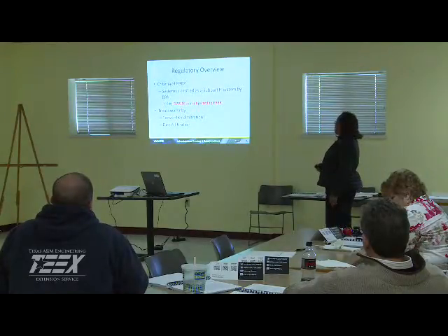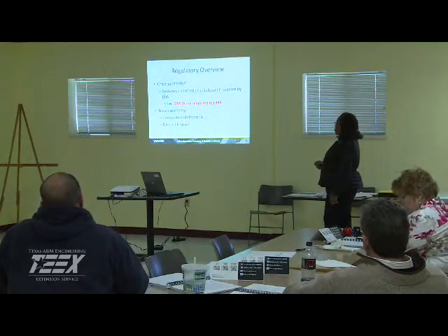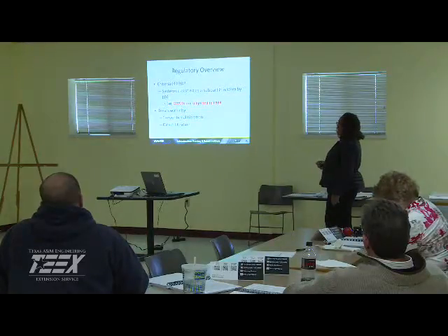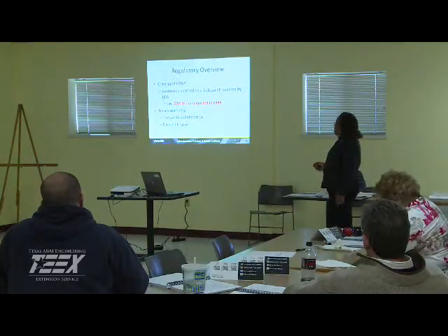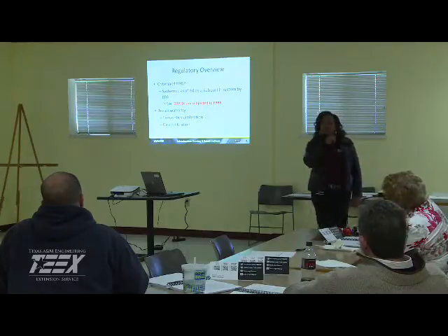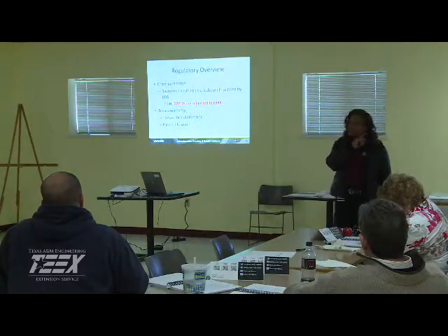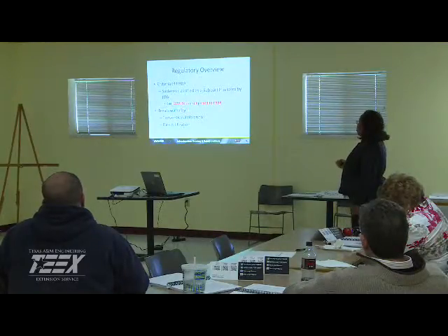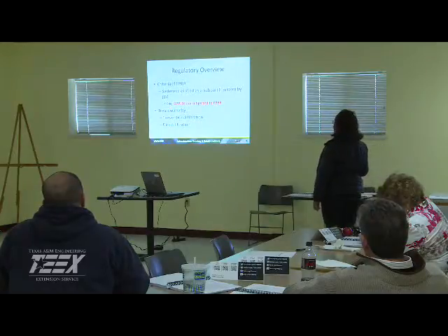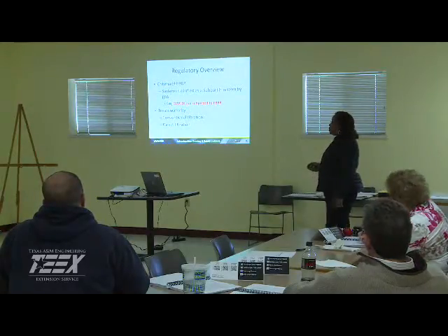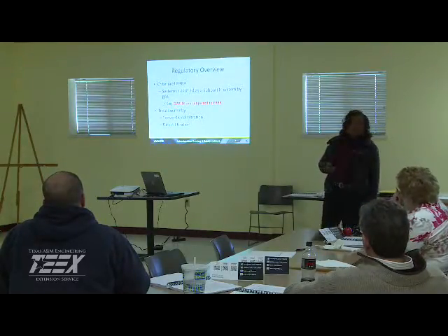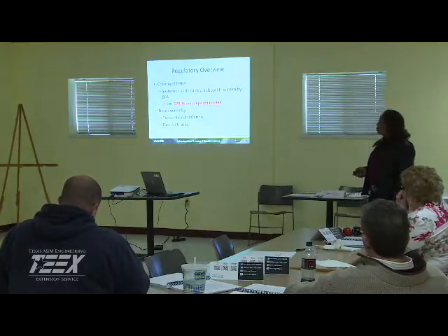Criteria of the FBBR: your systems are classified as a subpart H system by EPA. They need to make sure that they are adhering to this Filter Backwash Recycle Rule. And so what are the subpart H? We're talking surface water and groundwater under the influence of surface water. They are subjected to this rule.